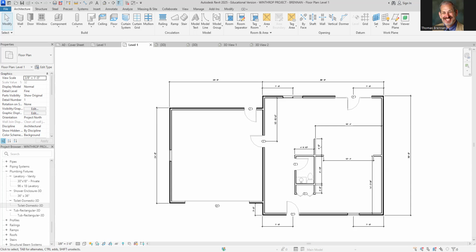But right now, if you go to your Modify tab right here, and then you go to Trim/Extend to Corner, it's the best tool. And we just click on this wall here, and then this wall. You essentially click on what you want to keep. And then these doors are all just kind of centered, right there, 2 foot 2 1/4 roughly. If you zoom in a little bit, you should be able to get pretty close.